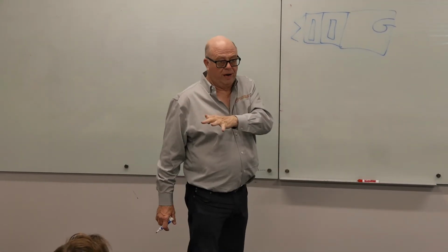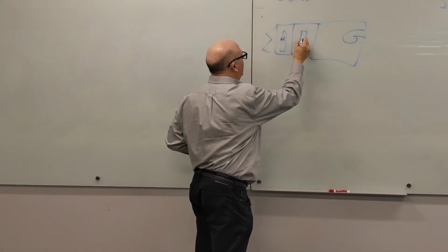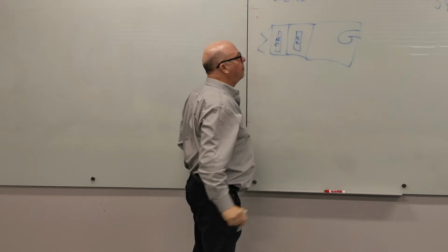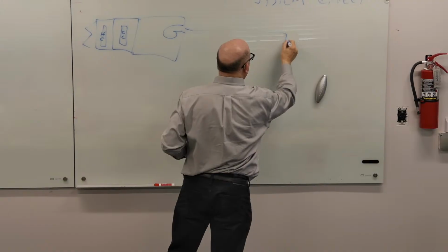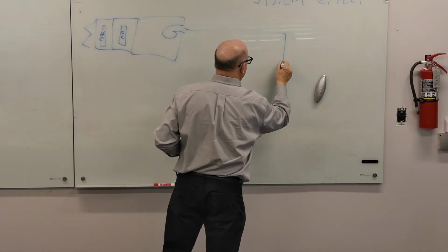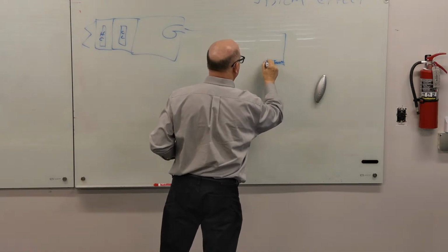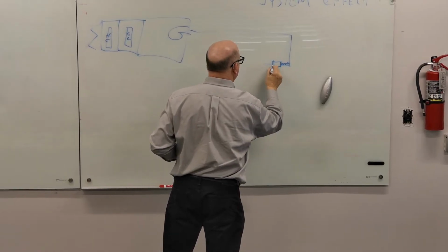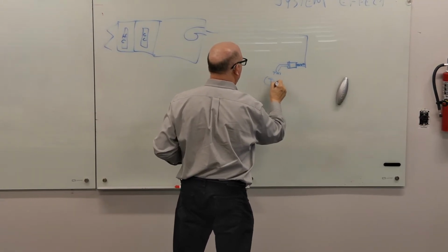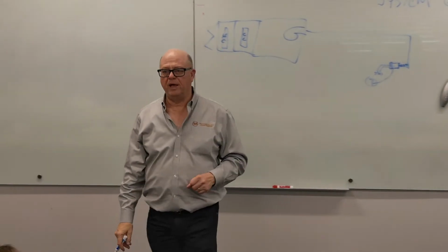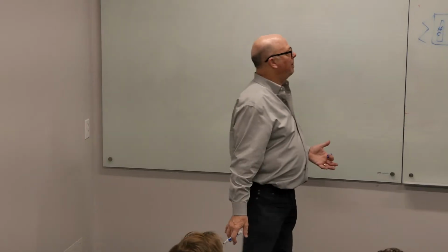But if you don't have a DOAS, then you've probably got a preheat coil here, and you've probably got a cooling coil. This goes out to a duct, and there's branches, and then you've got a takeoff to a VAV box, which let's just say it has a heating coil, and comes off and ends up going down to some diffusers. There's a stat on the wall or a temperature sensor or something. That looks familiar, right? This is what we do all the time.